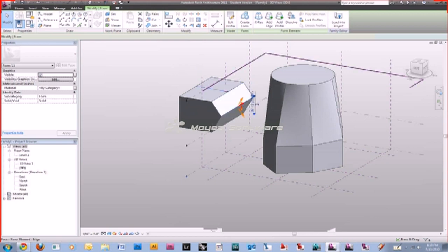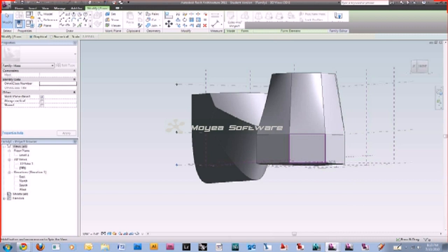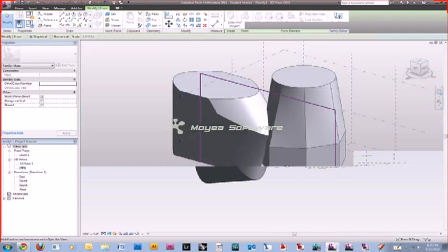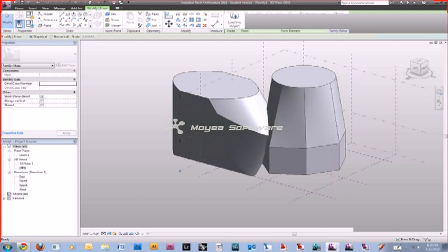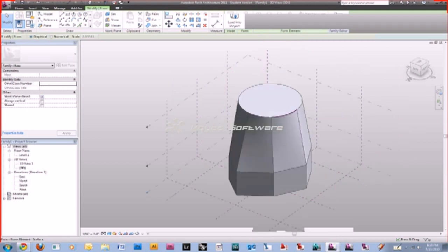All right, we're definitely going to get into that more in later sessions. But let's move on to the void command, which you've seen us skip past a couple of times. It basically does exactly what it says. It can void out the shape. It does have secondary preferences where, if you're adding or subtracting geometry, you can make the void become the solid and not the void. So you can let the void remain, and then you're taking away from the solid and deleting everything around the void. But in simple terms, the void can be used to cut into anything.